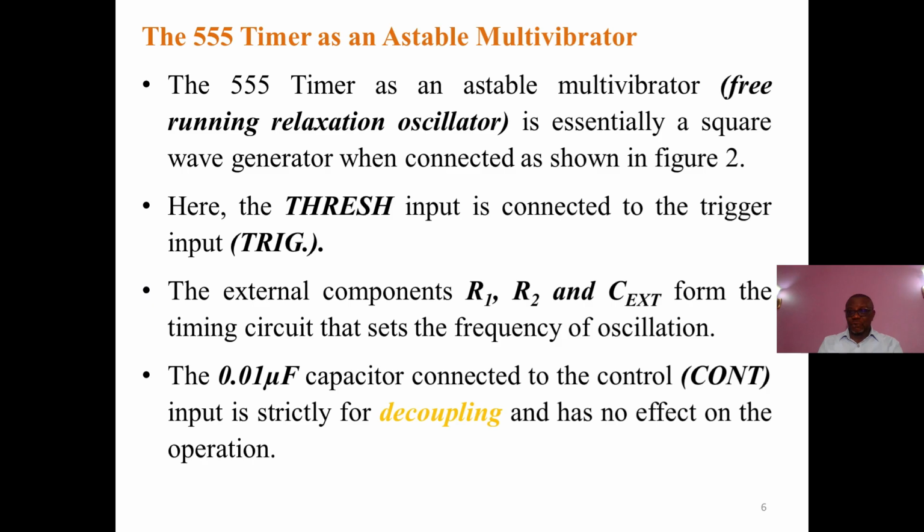Here, in that Fig 2, the threshold input is tied to the trigger input. The external components R1, R2, and C external form the timing circuit that sets the frequency of oscillation. The 0.01 microfarad capacitor, which is connected to the control pin or control input, is strictly for decoupling and has no effect on the operations.